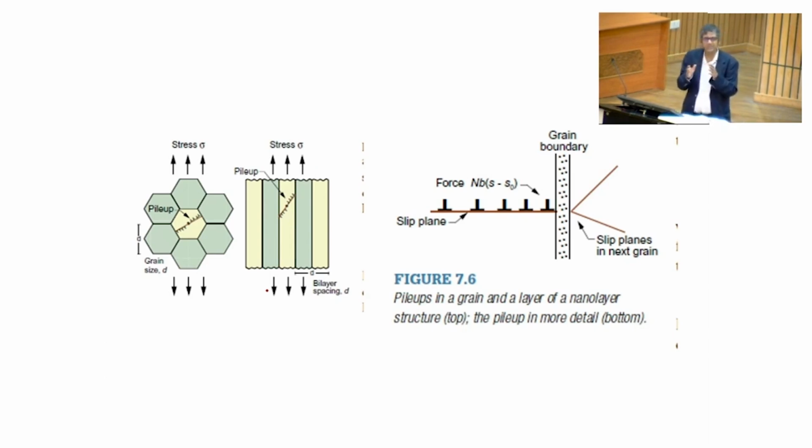They will feel jittery. Just like if you ask the humans standing in the queue to stand right behind each other, they will not feel good actually. They will feel that they are crushing onto each other. That's not good. Same thing is true for dislocations. So now if you keep on decreasing the grain size, what is happening? The length on which the dislocations can stand is decreasing.